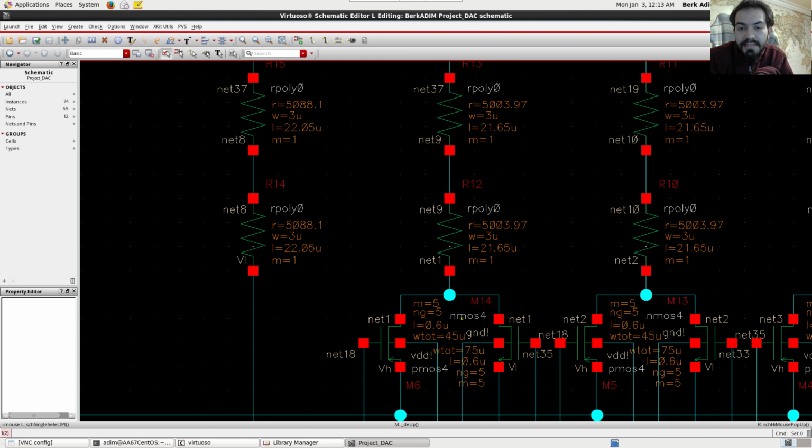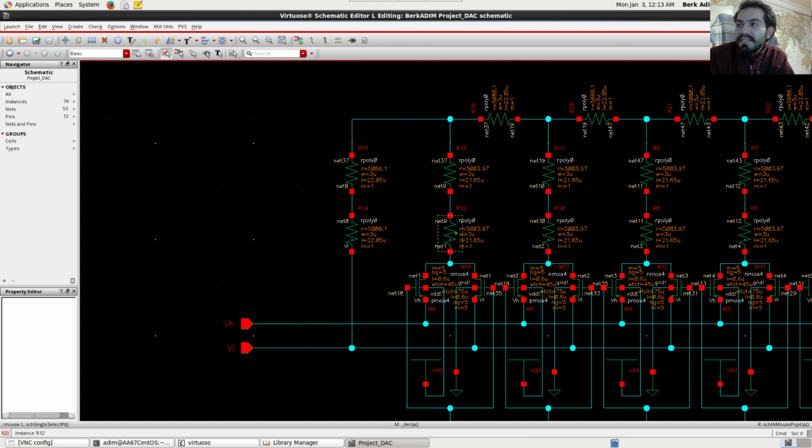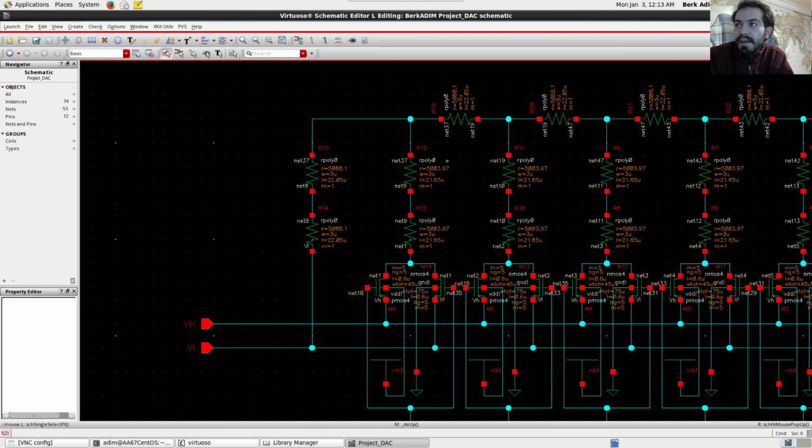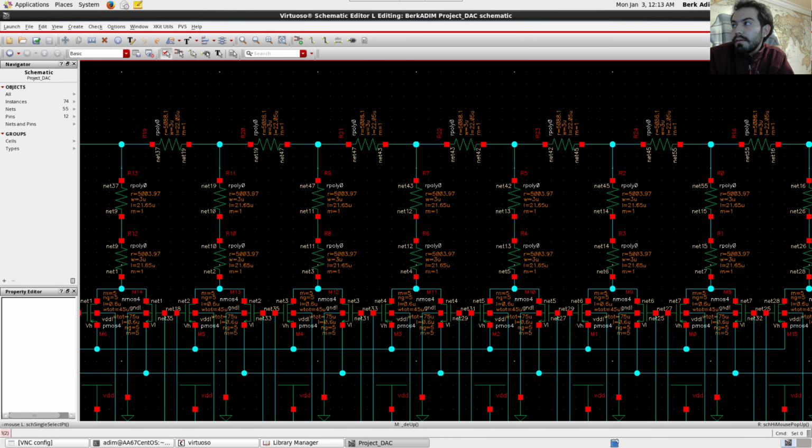When the state changes, the PMOS cannot transfer all of its charge to the NMOS, so it actually discharges over the resistive network and creates current spikes at our input.